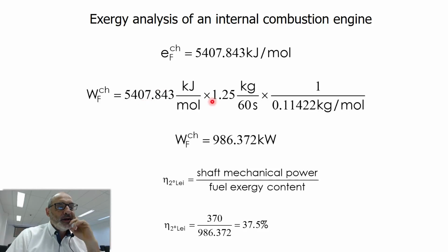And I'm just going to multiply by the flow rate because I don't want to work with specific quantities. So that's the exergy content times mass flow rate in kilograms per second. It was given in kilograms per minute, so 1 minute is equal to 60 seconds. And I have moles, I have kilograms, so I'm going to divide by the molar mass of fuel, which is here, the molar mass of octane.